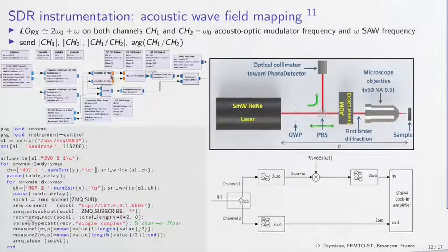So we will display the magnitude of the spectral component, as well as here is the division of the two spectral components, which will give us the phase output, so hence the phase difference between these two harmonic components, and all this data will be streamed to the laptop collecting the data.